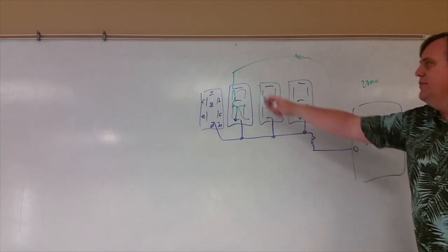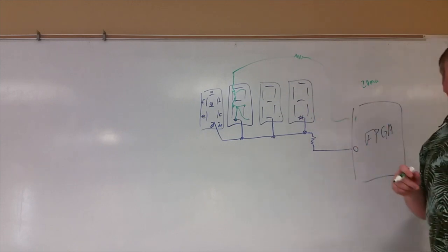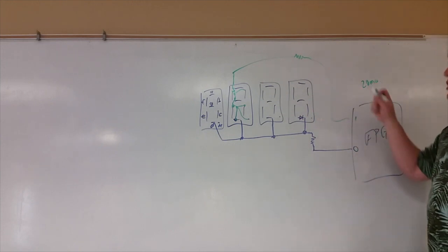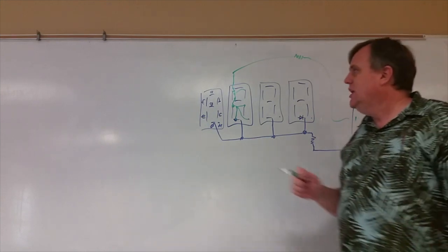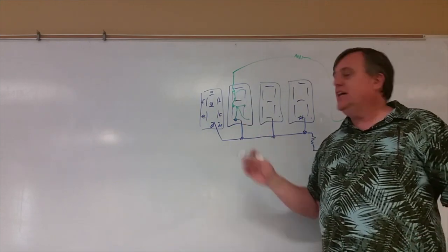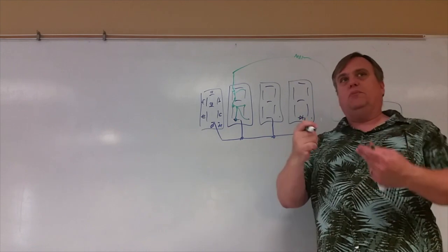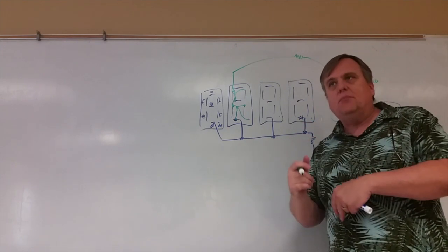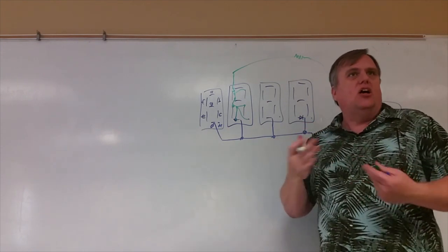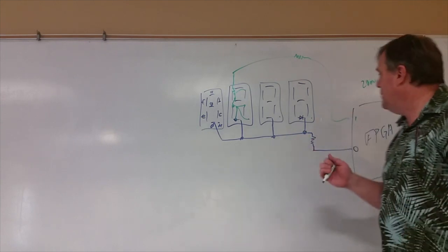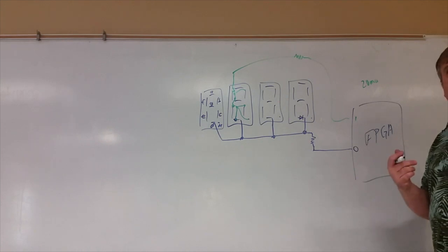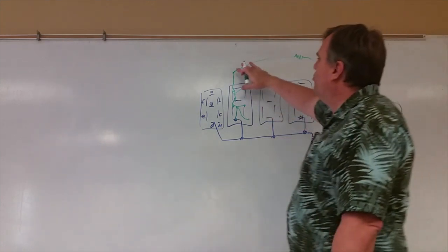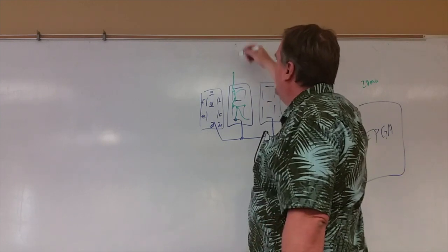That means each one of these devices, if they're all turned on, is going to get 20 over 8, or about 2 milliamps, which is not going to be very bright. So as you started getting more of them lighting up, fewer would be brighter, more would be dimmer. That's innately unsatisfactory, and it's just because this pin cannot supply enough current to do it. So I need to connect directly to my power rail, and that's why I need this.